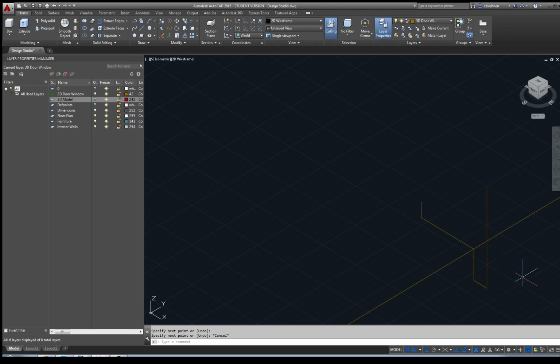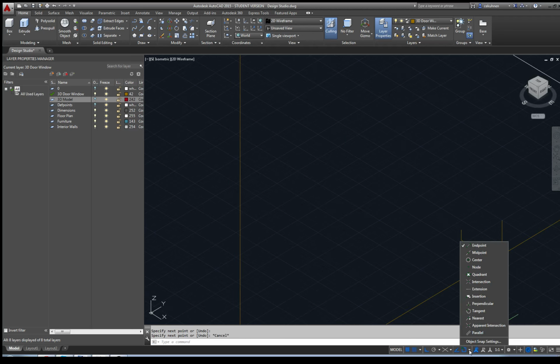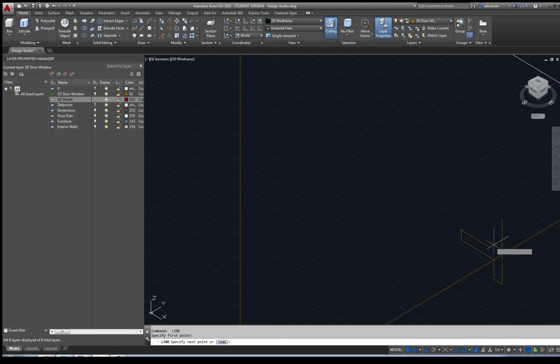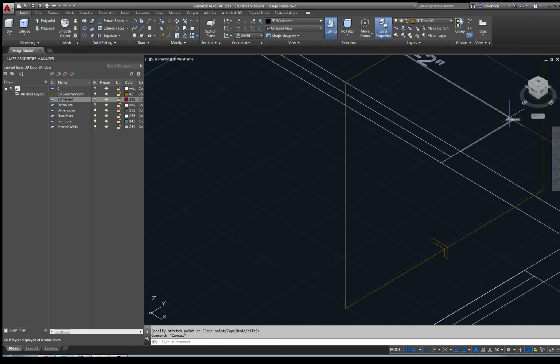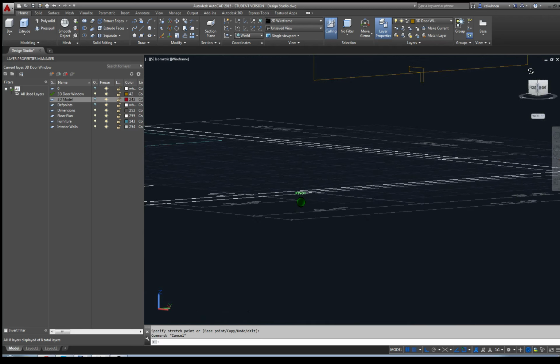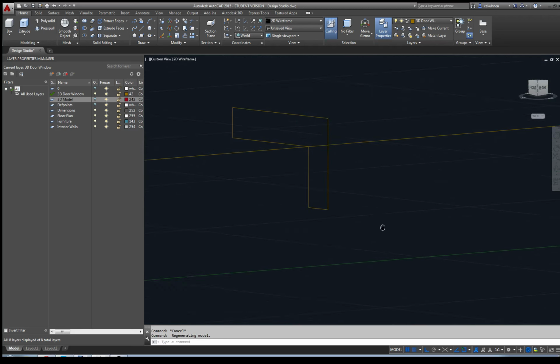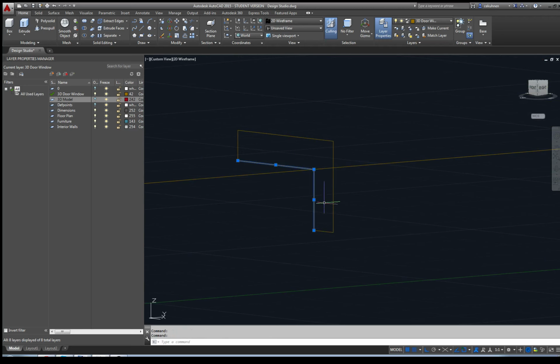Maybe I make it this tall. And then actually here I turn on perpendicular, spacebar U. See, there's a perpendicular snap, click, escape, because then I can move this one down to there. And there you see I created kind of like this cross section. So all this, select, and for example join. Here it is.